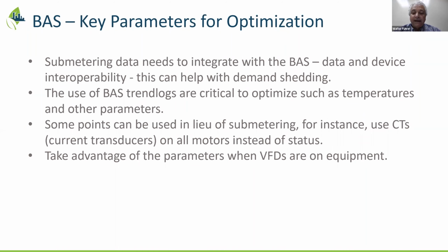Yes, Frank, we are. And you were correct. They were originally used for a status on-off. And now more and more we're seeing that you can actually measure current with them. For example, is the fan running? Isn't it running? And also you need a virtual meter to see the power consumed. Now, when you use a CT in this way, it's not an exact calculation, but over time, you can establish benchmarks and reference points quite simply by doing this. So if it's not a critical application, but you want to know what power is being used, it's a very cost-effective way to do it.